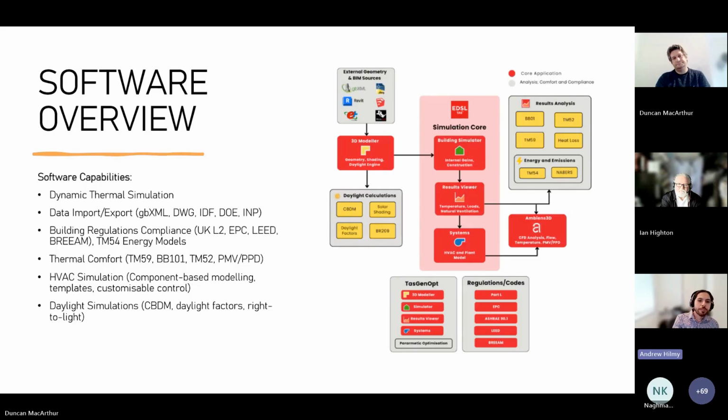So TAS has a number of core applications, and you can see those on the screen here. They're the red blocks. Normally you start in the 3D modeler, which is where you define your geometry. You can, of course, import geometry from Revit, Rhino, SketchUp, IDF, EnergyPlus, because we've got quite a lot of integrations with other packages. And then from there, you'd export your geometry to the building simulator.